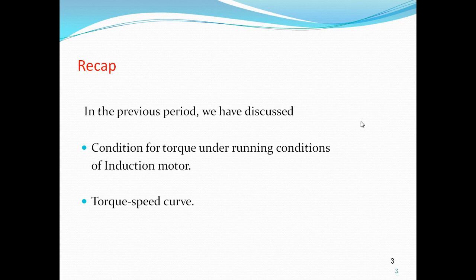For low values of slip, the torque slip curve represents a straight line. As load increases, speed decreases, slip increases, and torque increases.